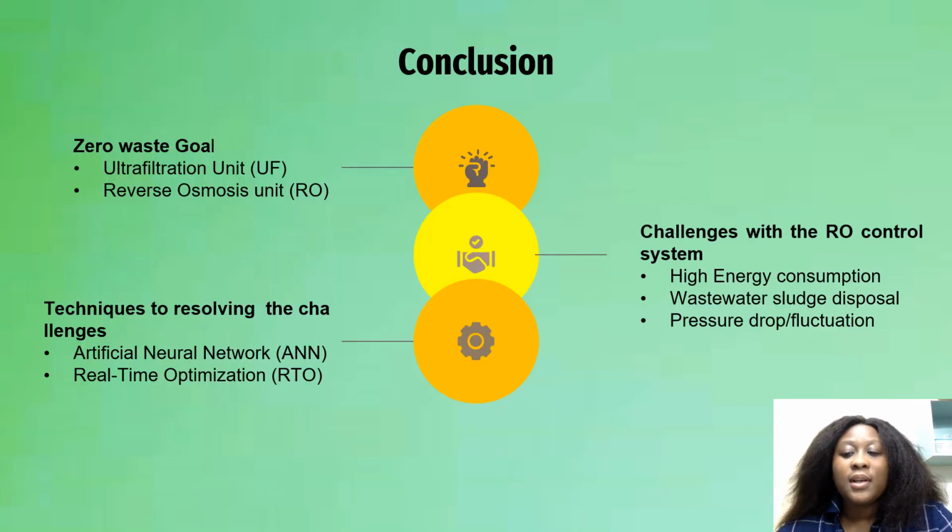Our group successfully discussed POME treatment from the palm oil industry, which is a waste management solution for the Malaysian palm oil industry. The discussion covers the environmental chemical engineering factors and the process control. To achieve the zero waste goal, our POME treatment process requires a few treatment stages such as pre-treatment to remove gross pollutants and safeguard downstream equipment, biological treatment to decompose organic matter, and a reclamation stage, which includes an ultrafiltration unit and a reverse osmosis unit that utilizes a reverse osmosis membrane separation process.